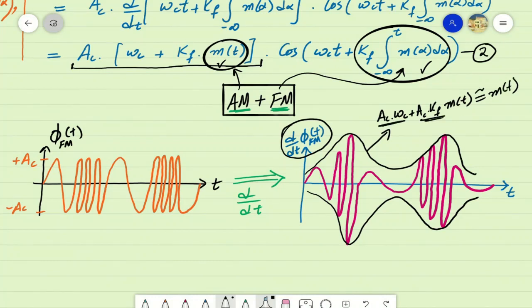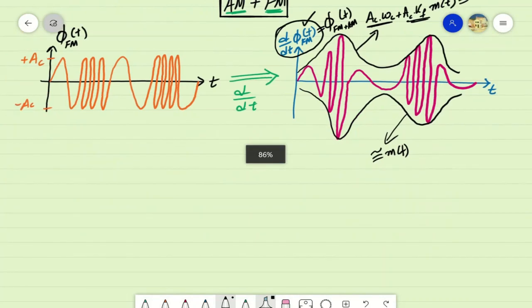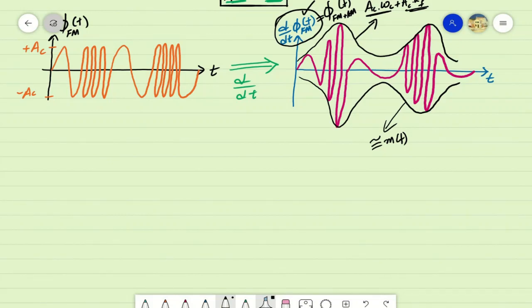So if we pass this joint frequency and amplitude modulated signal through an envelope detector, we can detect its envelopes, which are a direct representation of the information signal. As the information is clearly being represented on the amplitude of this signal, we can apply an amplitude demodulator to obtain the information signal from this signal.